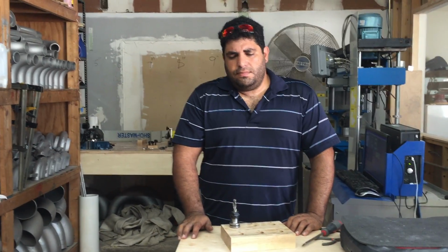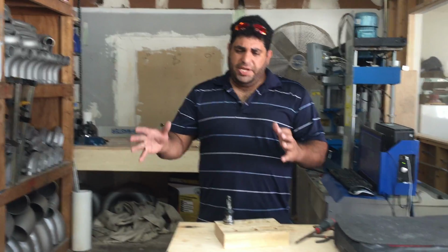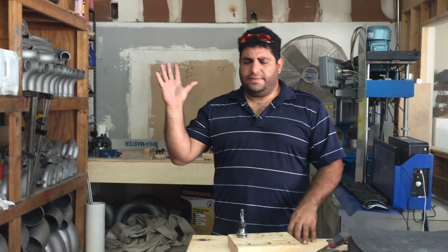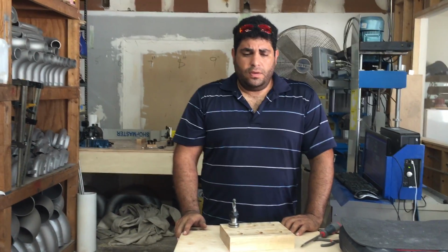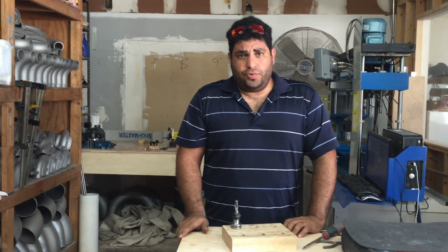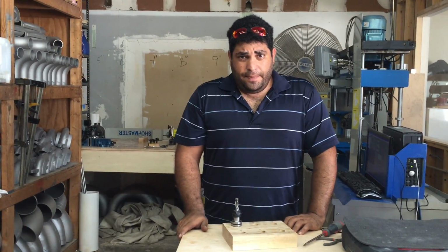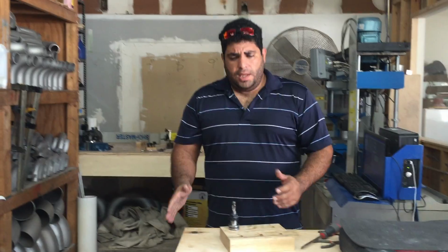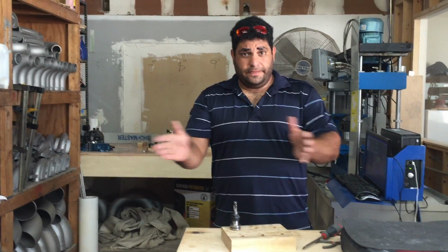And it's not really a calibration issue. If the machine thinks it will take 10,500 pulses to create 1 inch, but it's off by 50, it will still repeat the same mistake again and again and again.